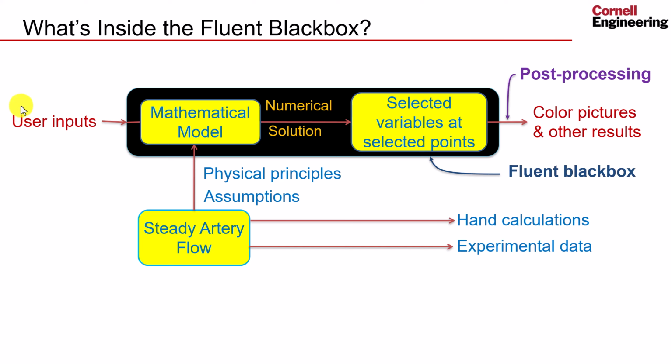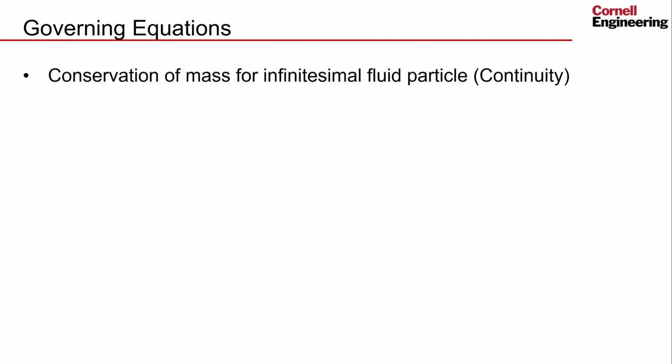Let's take a look at the mathematical model. This consists of governing equations and boundary conditions. For governing equations, we first have the continuity equation, which is conservation of mass applied to an infinitesimal fluid element. It is shown here in terms of derivatives of the velocity components.